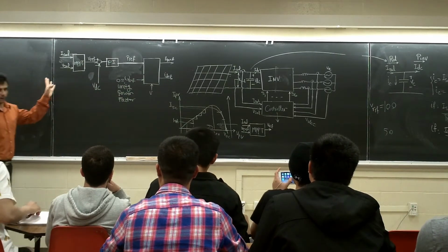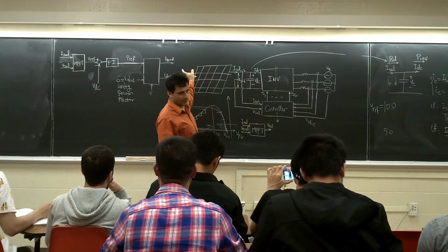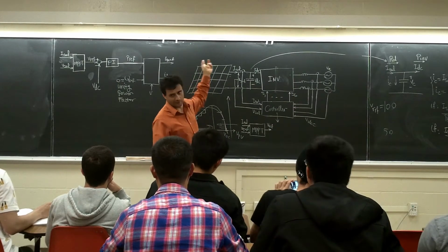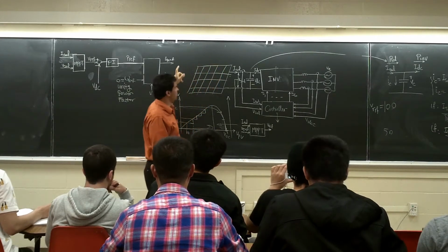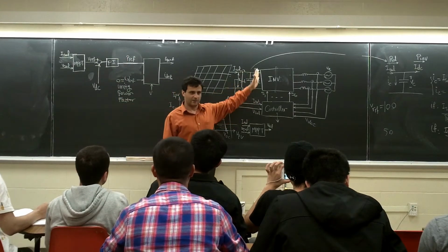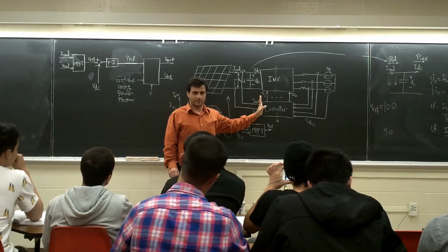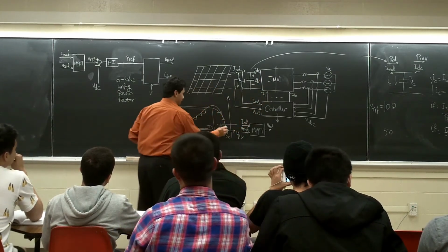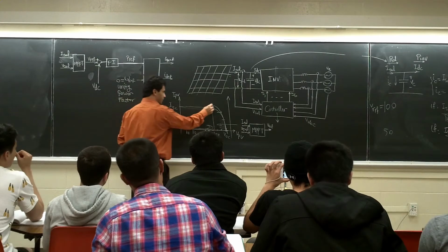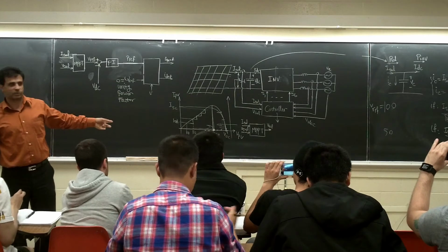So you add this to what you had before. Just instead of the PREF value in phase 3, where you set PREF to 50 kilowatt, 10 kilowatt, whatever is in the description. But in phase 3, PREF, because in phase 3 we have a battery here. When we have a battery, we cannot regulate the bus anymore. Whatever the battery voltage is, is the battery voltage, right? But when I have solar, I can work at any point. Where do I want to work? Here. Why? Because it will give me the maximum power generation.